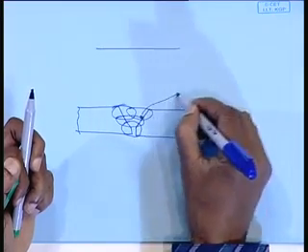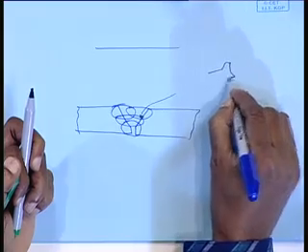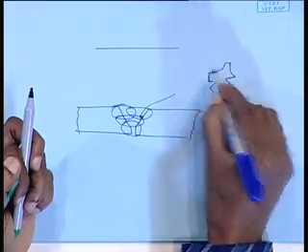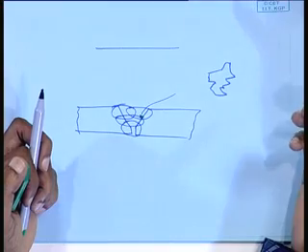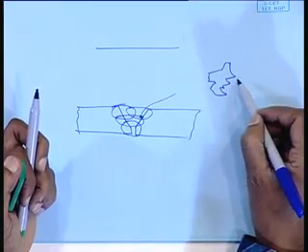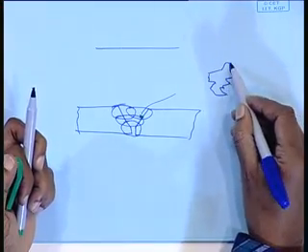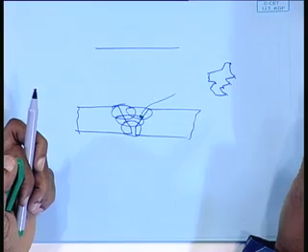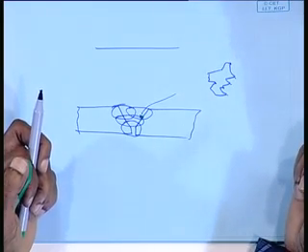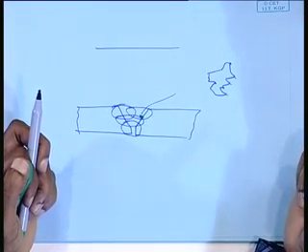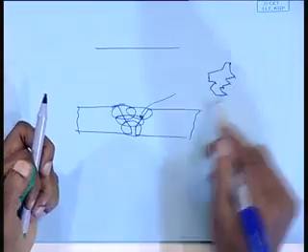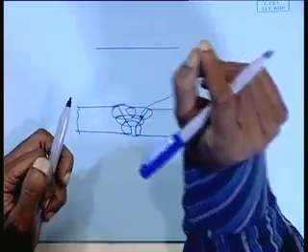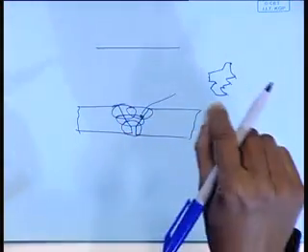If I look at it in an enlarged form, that slag particle can have any arbitrary shape, and in all probability that arbitrary shape will have very many sharp peaks. Why? Because the slag is a brittle material, it is the hardened, burnt flux. So a small speck remaining means it will have all kinds of sharp edges.